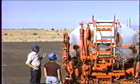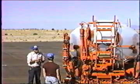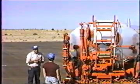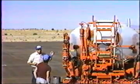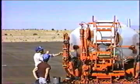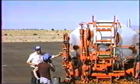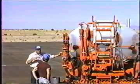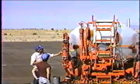Now this truck has computerized rate control. Since we use the computer to totally regulate the spread rate, we're not going to use the bypass valve at all to regulate spread rate on this machine. So on this machine, that valve works strictly as an air-operated relief valve, and we're just going to refer to it as the relief valve at the end of the piping system on the spray bar.